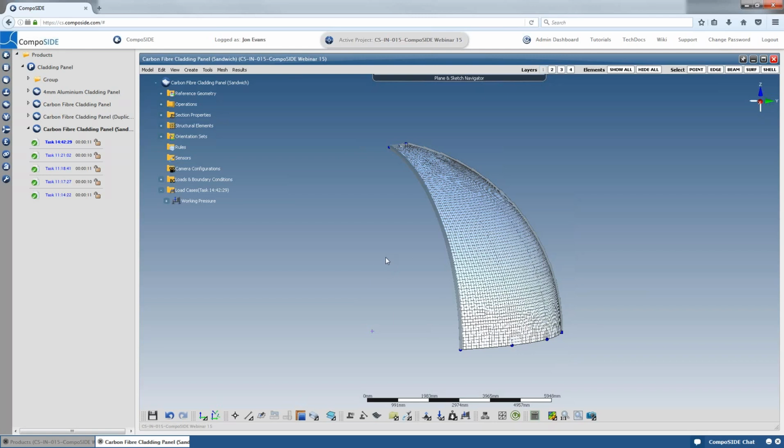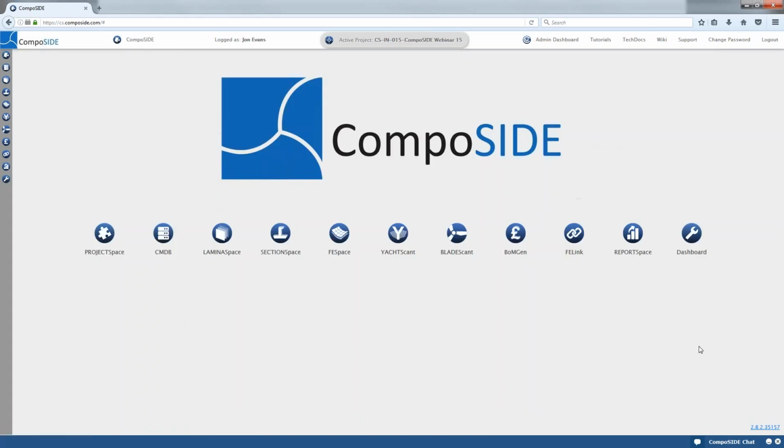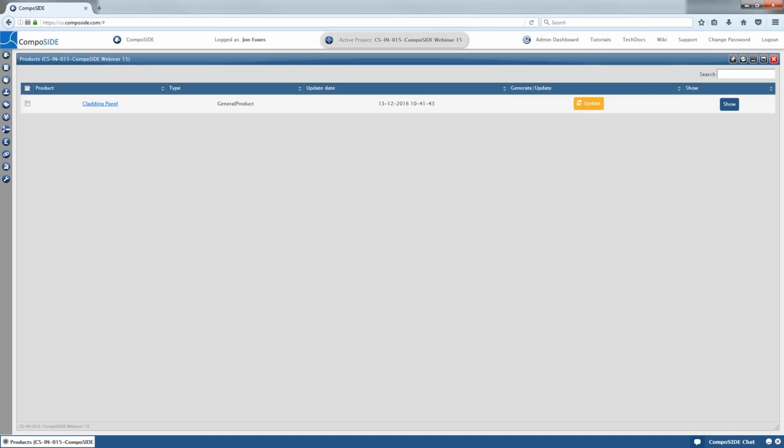So if I want to generate a bill of materials, which I mentioned in the beginning, this is the final step. Usually your boss asks you for a report, or you have to give it out to a customer as a deliverable. Instead of taking all of that data and putting it in a spreadsheet, applying your manufacturing values and core offcuts, ply offcuts, adding all of that, what we can do is go into PlyGen, and then we can generate a bill of materials.